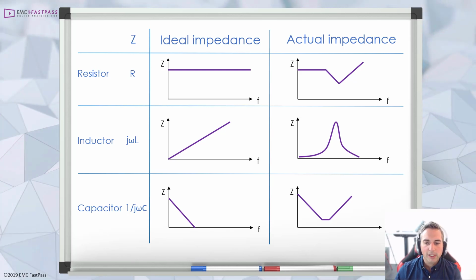So in the example simulations we just looked at, what we're seeing is that the current is flowing using the minimum amount of energy possible. And luckily for us, the path that the current naturally takes is the path that minimizes the amount of energy contained within the electric and magnetic fields. In an analogy that Keith Armstrong uses, he's another EMC instructor, he compares this behavior to a water droplet in air, which always assumes a spherical shape, and that's nature's way of minimizing the energy in the surface tension on the water.